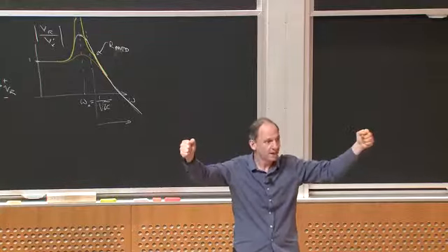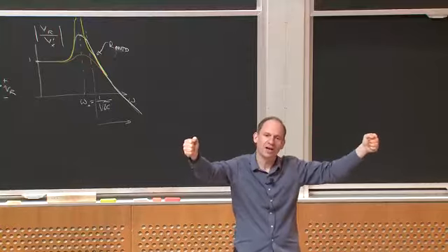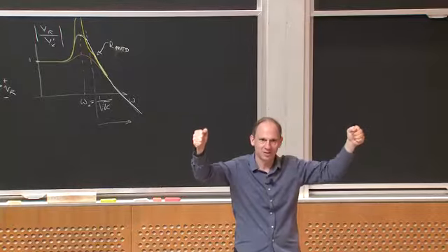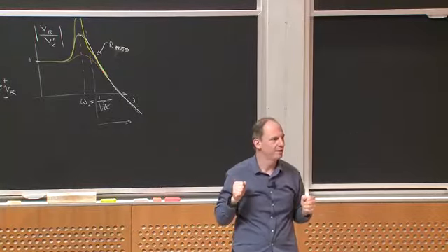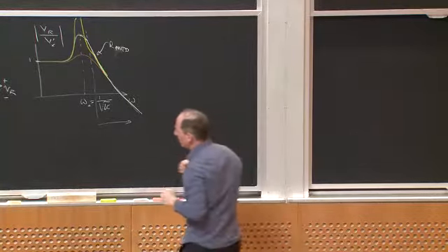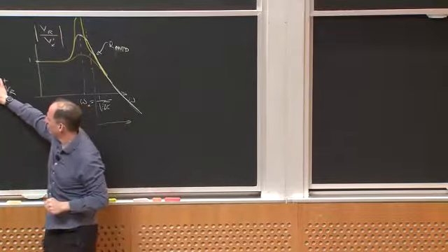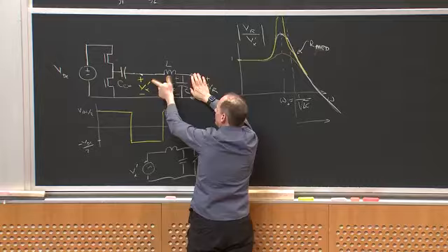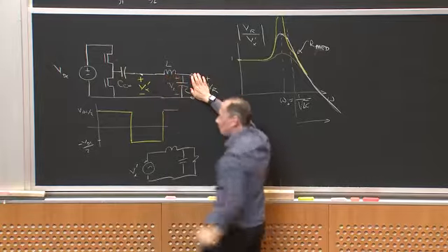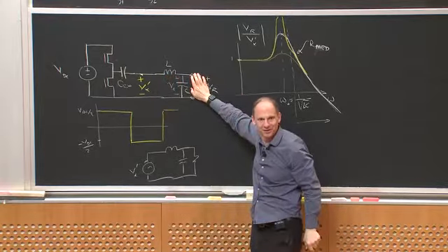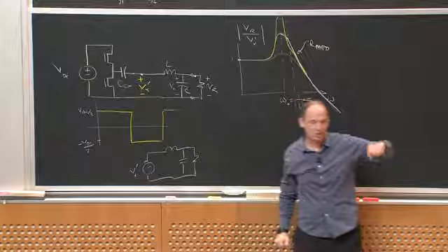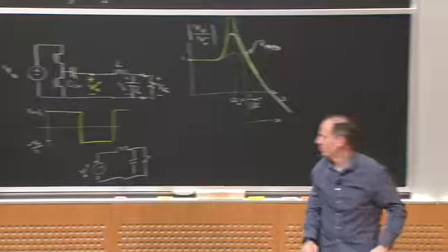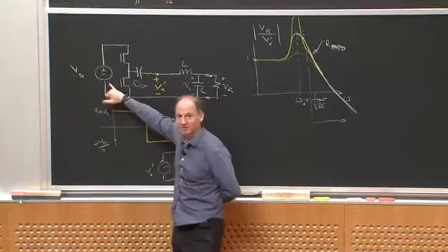And you've got to get a really, really big voltage on it to break down the gas and so-called strike the lamp. Well, how can I do it? If I take this thing as an open circuit and I drive this half bridge right near the resonant frequency of L and C, I'm going to build up a really big capacitor voltage here. That capacitor voltage could be tens of times as big as my DC voltage.